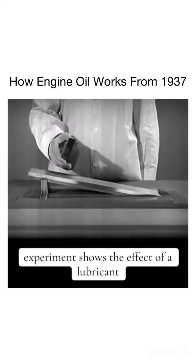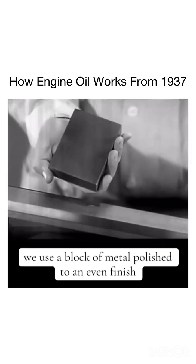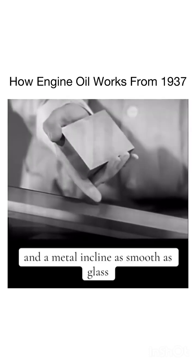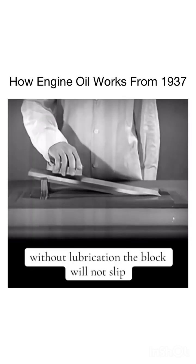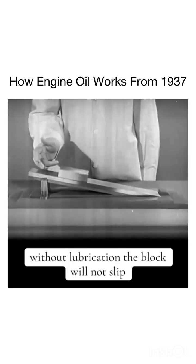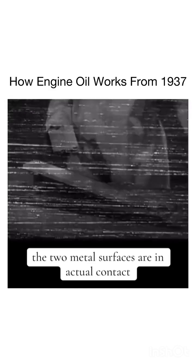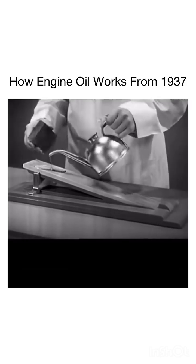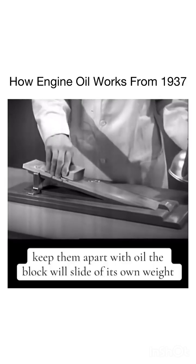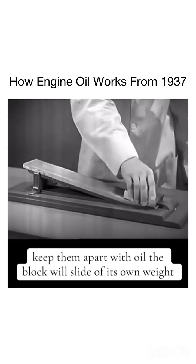This experiment shows the effect of a lubricant. We use a block of metal polished to an even finish and a metal incline as smooth as glass. Without lubrication, the block will not slip. The two metal surfaces are in actual contact. However, if we lubricate the same surfaces, keep them apart with oil, the block will slide of its own weight.